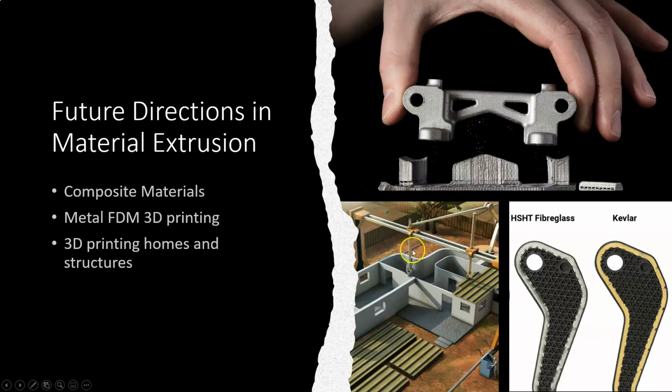So the filament, quote unquote, the filament that you're going to be printing is going to be cement, right? And the cement has the correct consistency, so it's not going to just flow very easily. It's kind of like a more solid, if I can use that term, cement that's pumped in. You can see the crane here that's pumping the filament down into the print head.